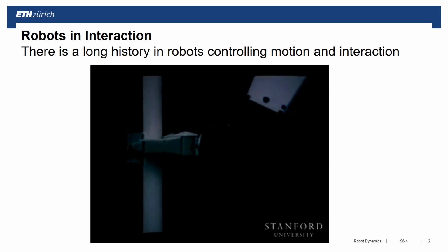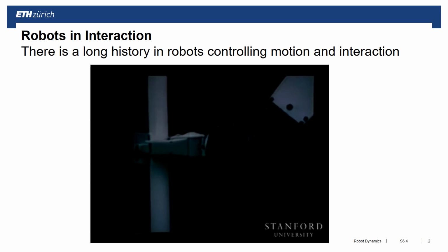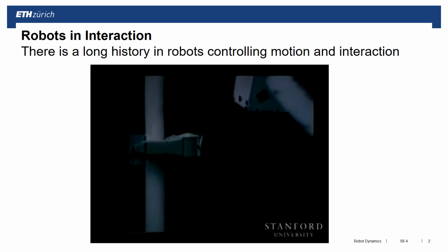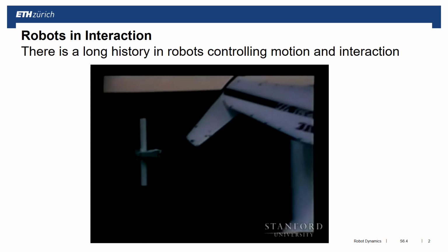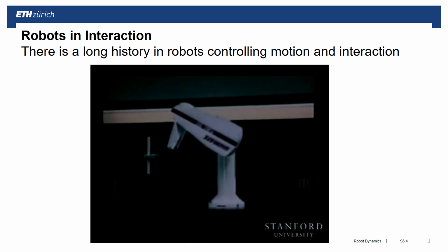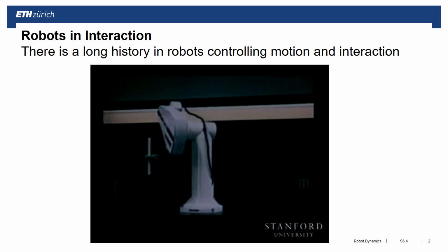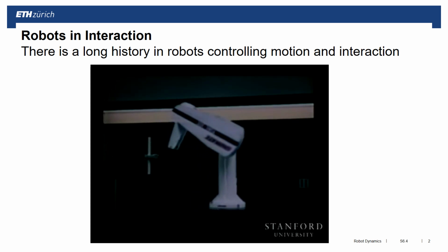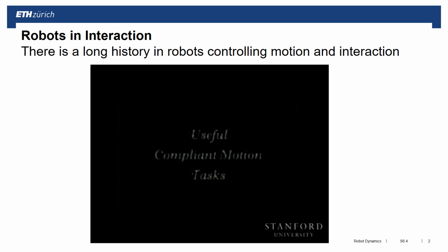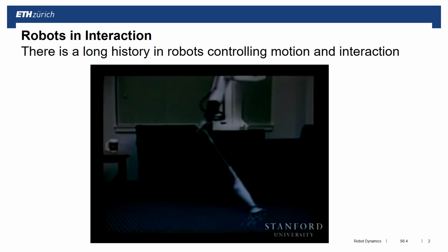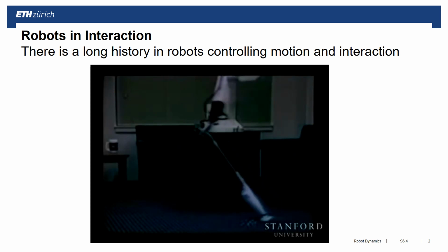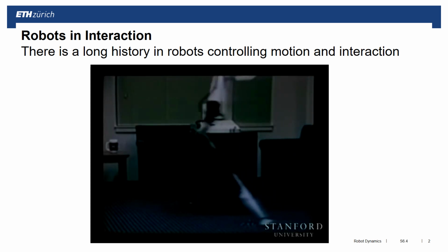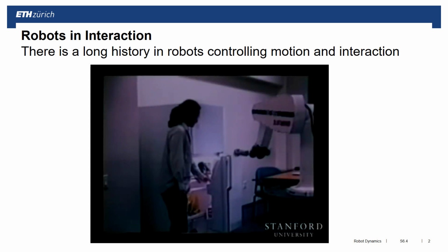And the speciality of it is that in some directions, these robots typically control the position, while in other directions, they are regulating interaction forces with the environment. There are several examples where this is pretty useful. For example, if you have a robot that is hovering your environment, obviously this robot has to produce a motion in XY direction while it produces a certain force in Z direction. So it's a hybrid task.